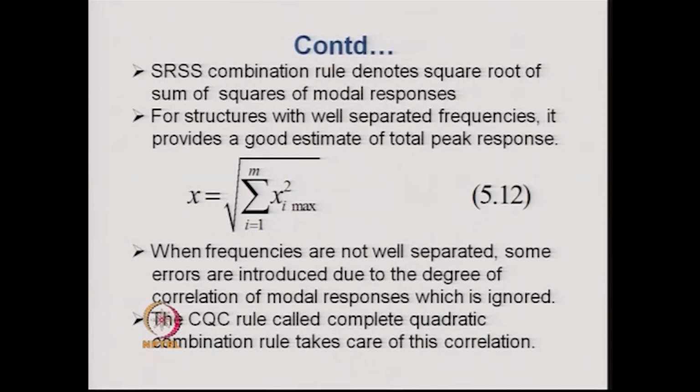Now, this particular formula is valid when frequencies are well separated, that is, they are not close, because if two frequencies in the two modes are very close to each other, then it is expected that there will be a correlation between the responses of the two modes.